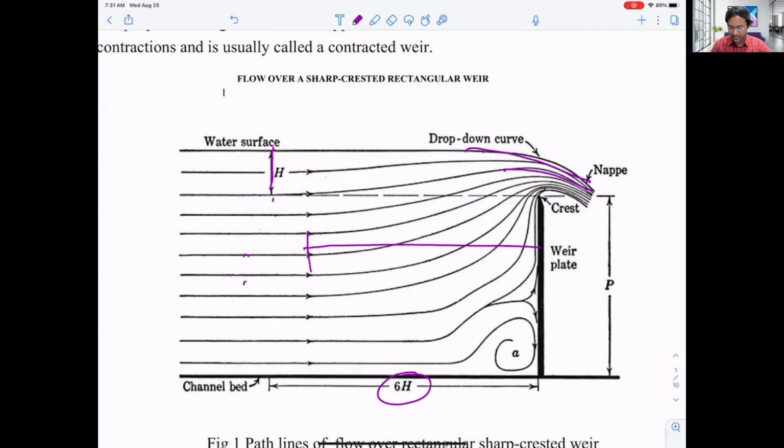If we measure like 5-6 feet away from the weir, we can get a perfectly horizontal surface of the water. Then our reading will be more accurate than on an inclined surface. And since the water flow will be higher, there will still be some undulation right here, so we have to take an average measurement.